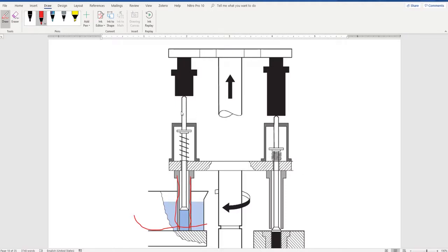Now the dosing tube goes into the powder. Then the spring-loaded piston will compress the powder, because if it doesn't do that, what happens? When the dosing tube goes up, the powder will fall down. So the job of this piston is to compress the powder into the plug. Because of compression, the plug will be formed and it will stay inside because of pressure.